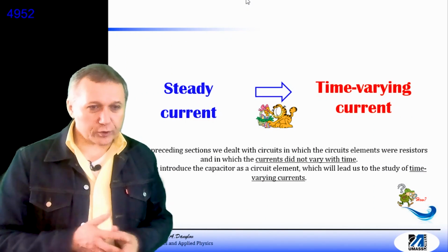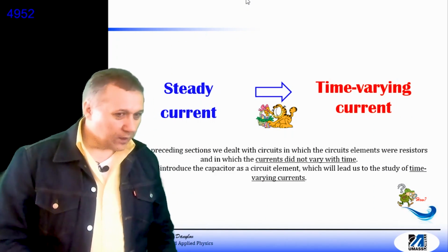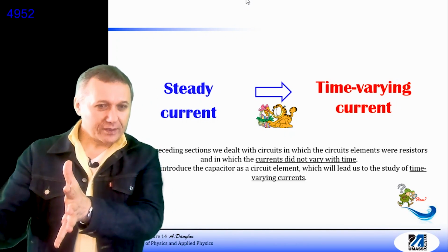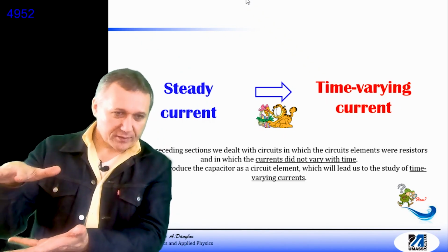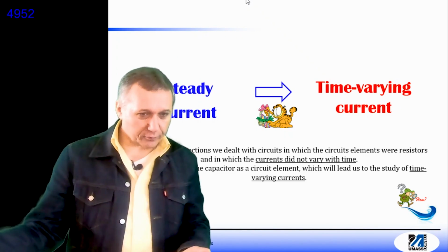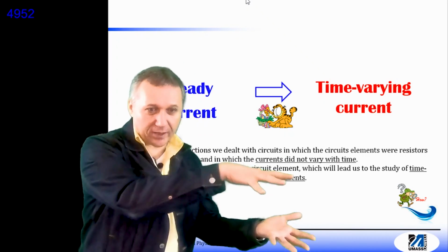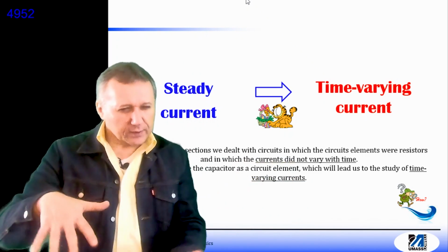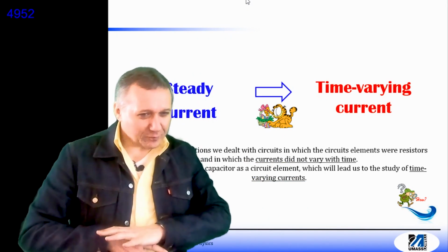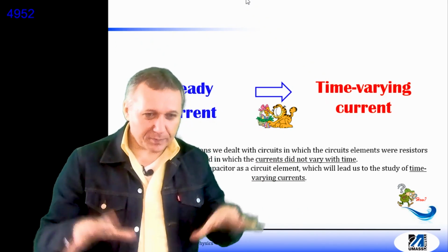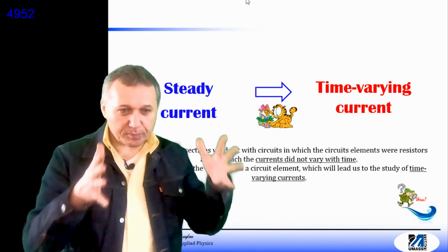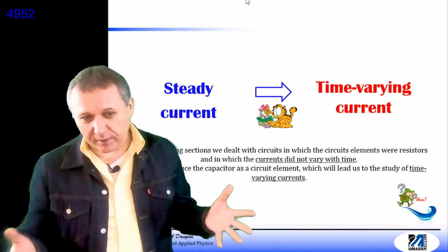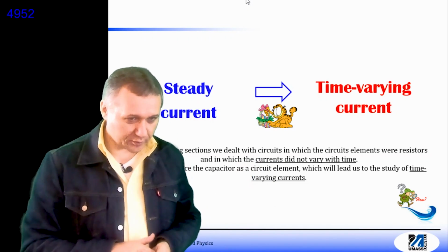So how are we going to change current? There will be a capacitor, first an empty capacitor, and of course we can charge that capacitor. In order to charge it, we need to have a source of charges, a battery. If we connect a battery directly to a capacitor, the process can be too fast, and we can damage our capacitor. So it's better to slow things down, and connect them through a resistor. So the current will be reasonable and we will not cook this circuit.